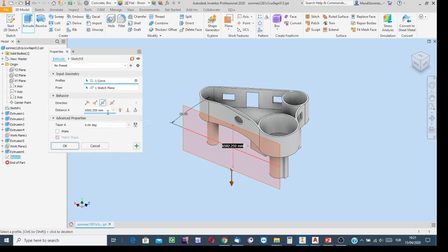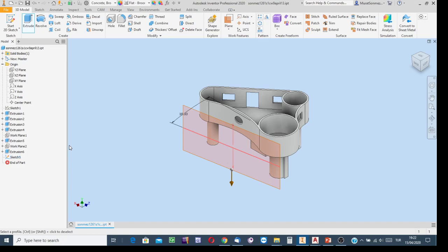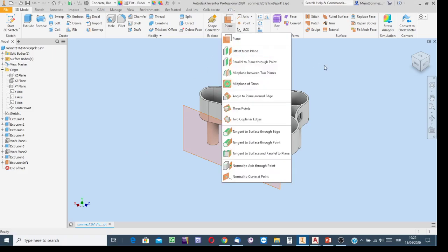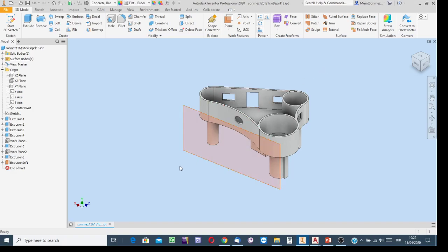Do not pay attention to this number. It may be set in order to make the work plane distinguishable. You know, this is going to be used for coinciding the sketch plane. Sketch plane is unlimited. So just finish this surface creation stage, and here is my work plane. You see, I created the work plane, not invoked. Using this facility you can invoke a work plane. But here I created the work plane and its orientation is correct. This work plane is perpendicular to the direction of the cutting extrusion process.